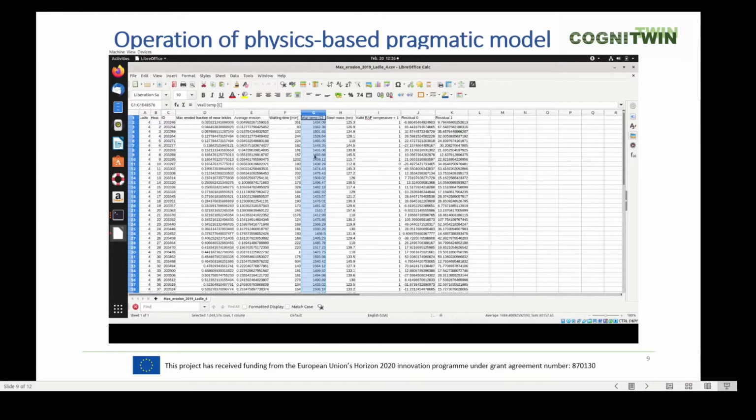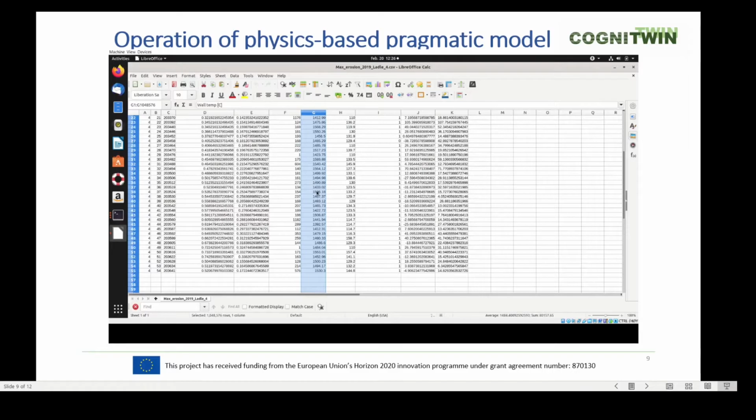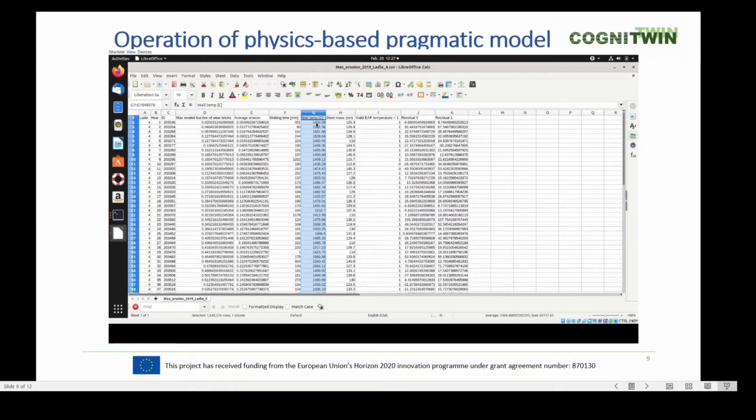And these temperatures are important for thermal degradation, because if the ladle is cold and the metal is always well above 1600 centigrades, there will be quite some thermal or thermomechanical erosion when the hot metal hits the bricks in the ladle or gets in contact with the bricks.